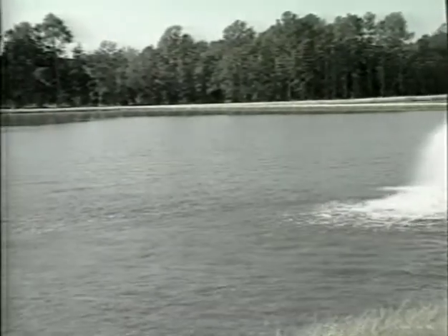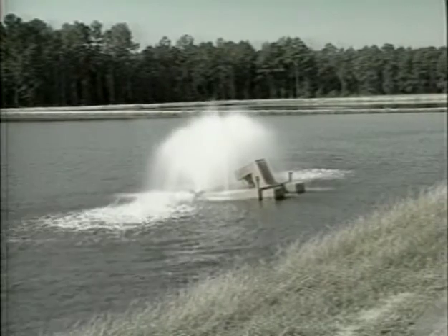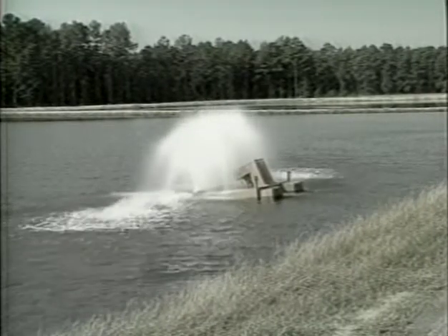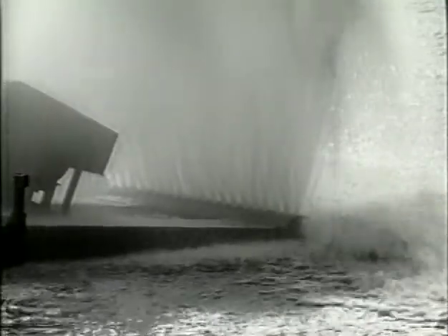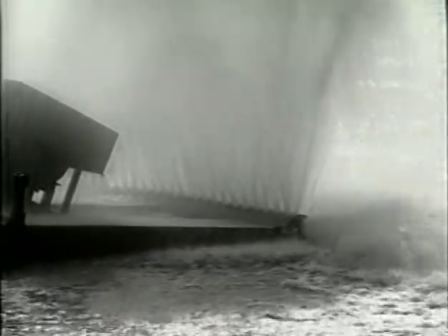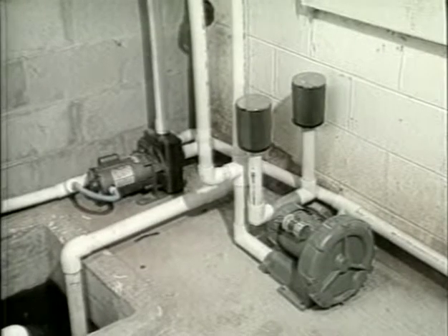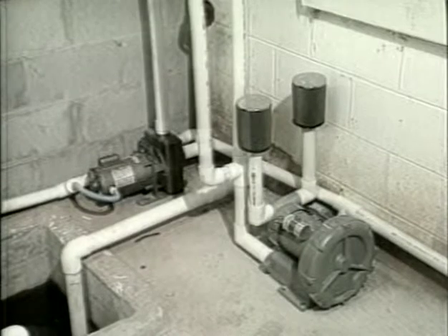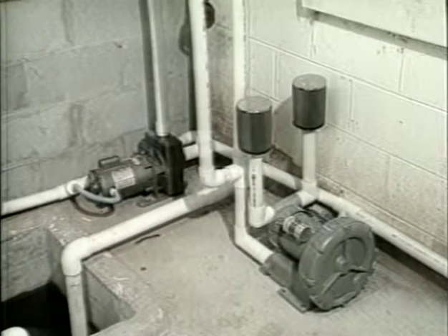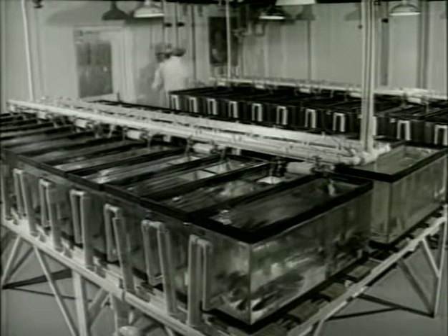The principle behind all of these aeration devices is exposing small bubbles of water to the air, thereby increasing the surface area for diffusion. As water is splashed, more of it is allowed to contact the air, thus promoting diffusion of oxygen into the water. Another type of aeration is accomplished by devices which move air or oxygen into the water, such as air blowers. These are usually not practical in pond culture, but are commonly used in holding tanks and hauling containers.